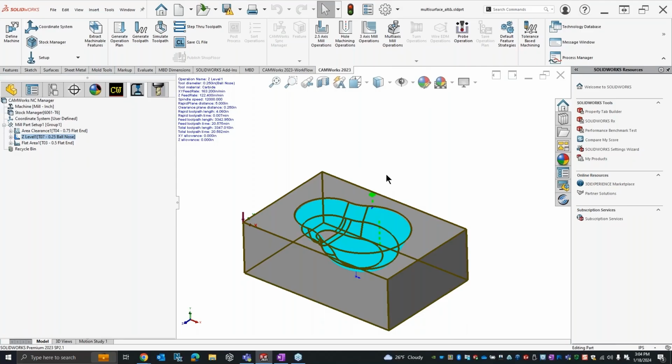So some of the CAM systems will allow you to put basically a manual text that will get printed out or posted out with all the other operations. So before the probing operation, let's say I want to preset some variables, whatever, number 66 to 50, number 67 to 75, or what have you, I could put that in the tree and that would get posted out with all the other operations. I'm not sure if that makes sense.